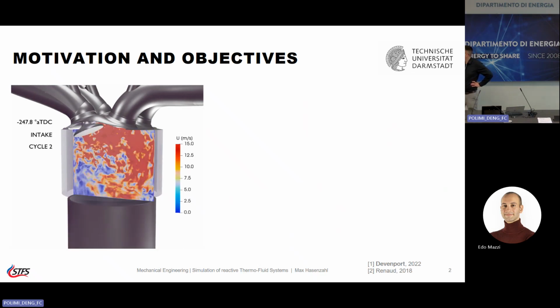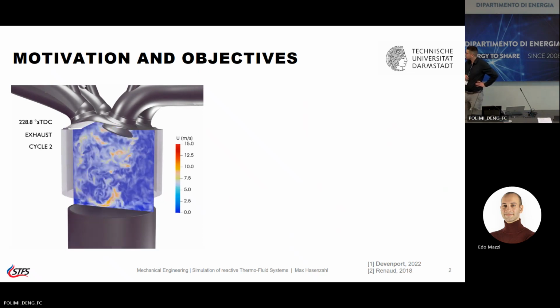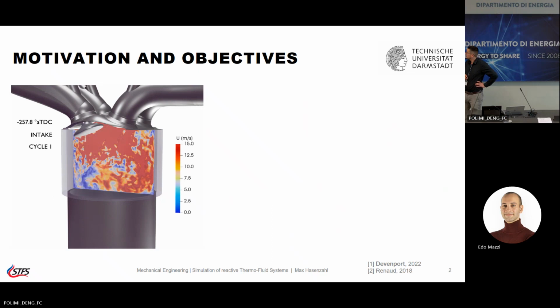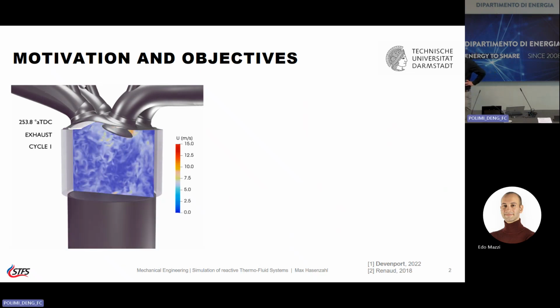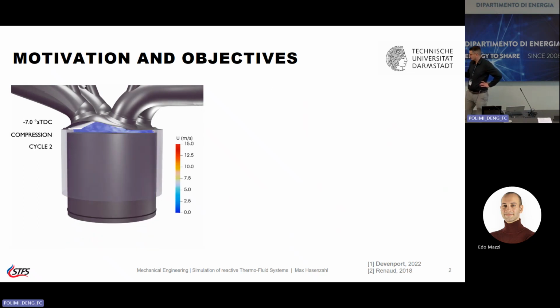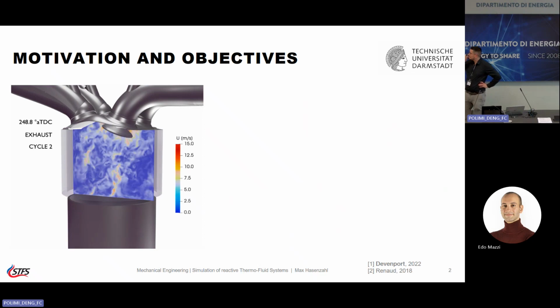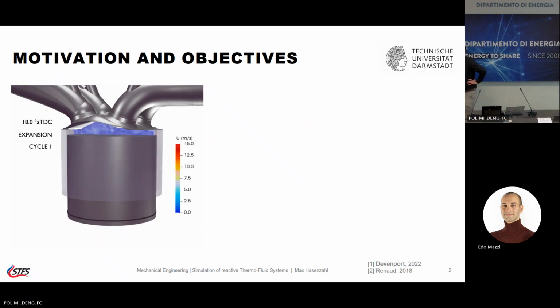It's an SI engine, 86 millimeter stroke, 86 millimeter bore, and 800 cc's. And this particular operating point that I'm showing you here is at 800 RPM, motored, no combustion.